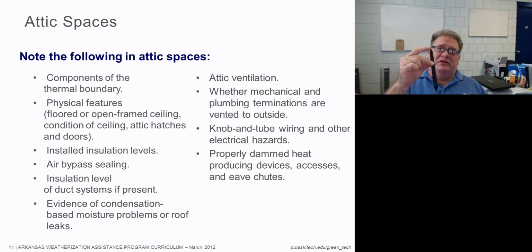Sewer gas will exchange with the air that's around the opening of that vent pipe. So that needs to be outside the house. We can have methane and other really ugly gases build up in the attic. The other thing is we don't want to cover those with insulation. If we block them, then the drain pipes will not work properly. So those need to be terminated up through the attic roof.